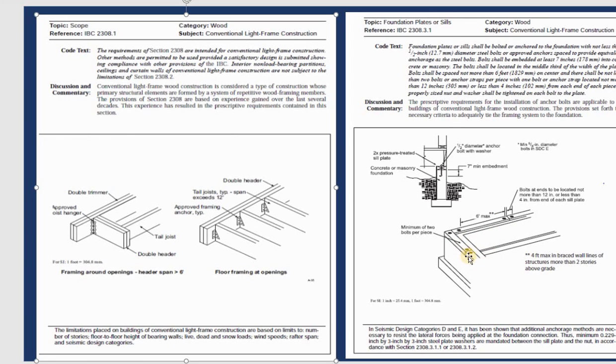And the distance, when you go with the bolt, the distance between the bolt and the bolt should be 4 inches from the edge, from this bolt to the other one. And this one they have 6 inch maximum. You need to have one bolt, and after that the next bolt right here needs to be 12 inches, not less than 4 inches. They can do from 4 to 12 for the distance before you go with another bolt. So basically 6 maximum. And if you go more than 2 story, then the distance can be lower, say 4 inches maximum between one bolt and another.